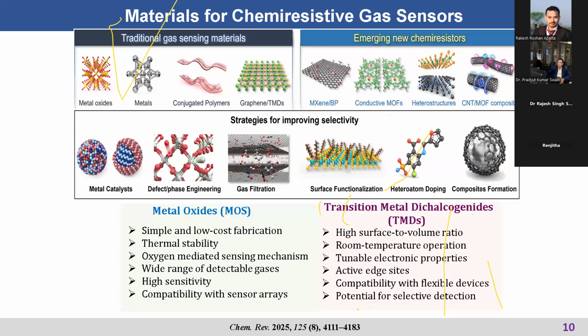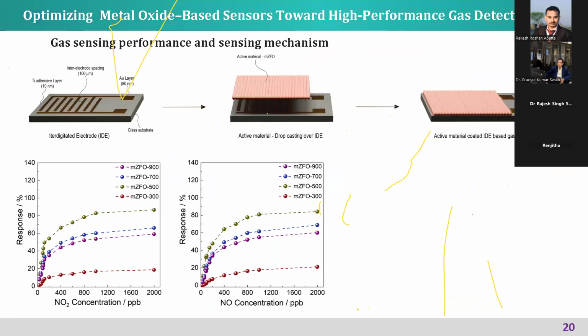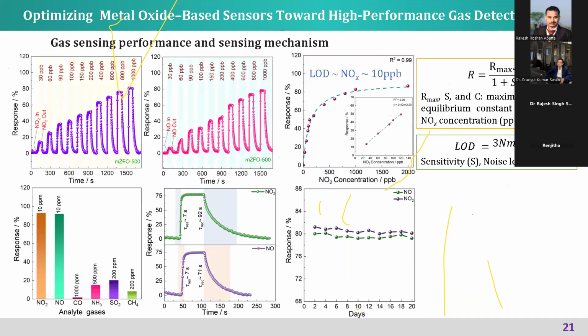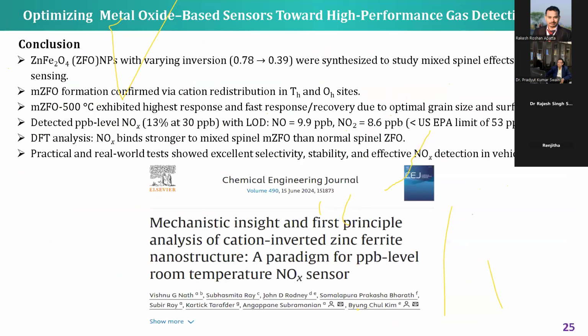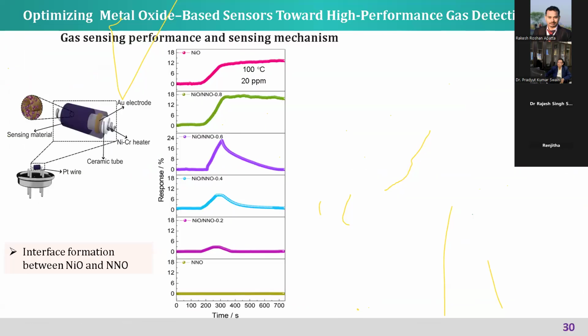If you see our second study, NdNiO3, for the SO type of gases. In these sensors, we have to have heating. A room temperature sensor will not work at all. The sensor will not come to the ground state, I mean, the original state, when the gas is removed. So room temperature is not possible at all. So one has to use the heating.